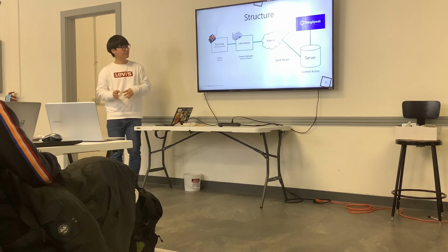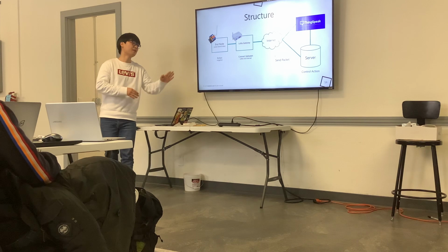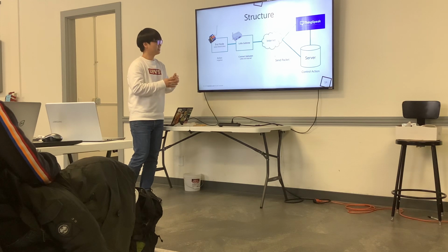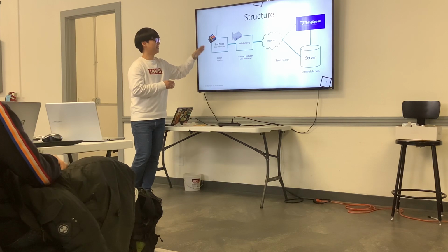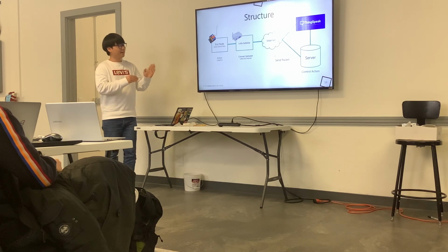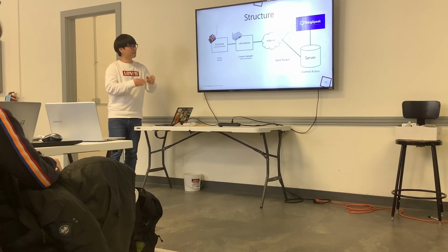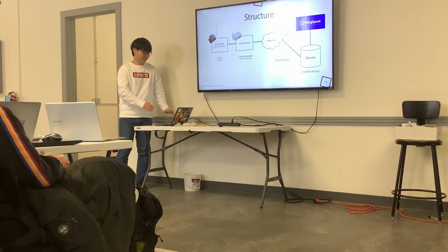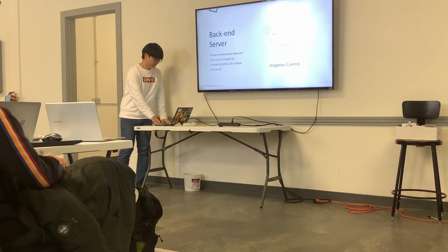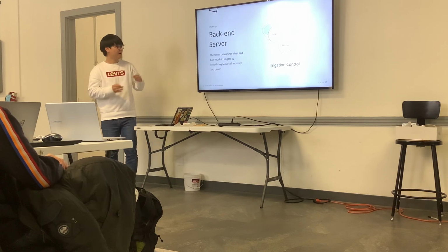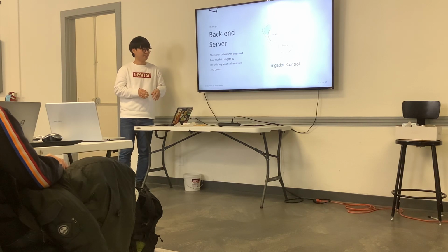Then, how about irrigation control? First, the server observes the data. When the data matches the irrigation conditions, the server sends a packet to the gateway. Then, when the Bridge library receives the packet, the gateway passes the packet to the end node. Finally, the end node begins irrigation. The server determines when and how much to irrigate by considering MAD, soil moisture, and period.